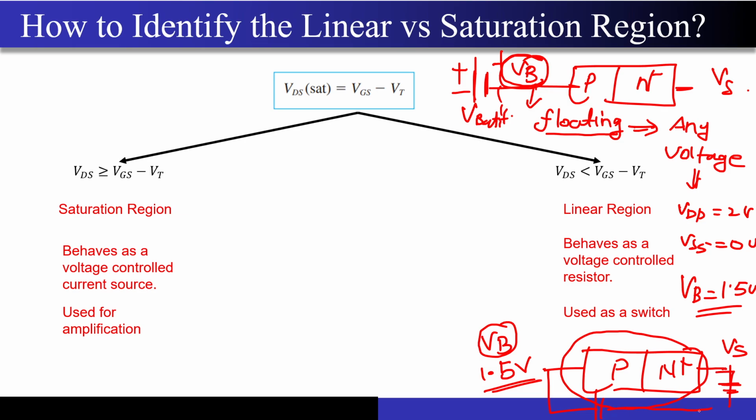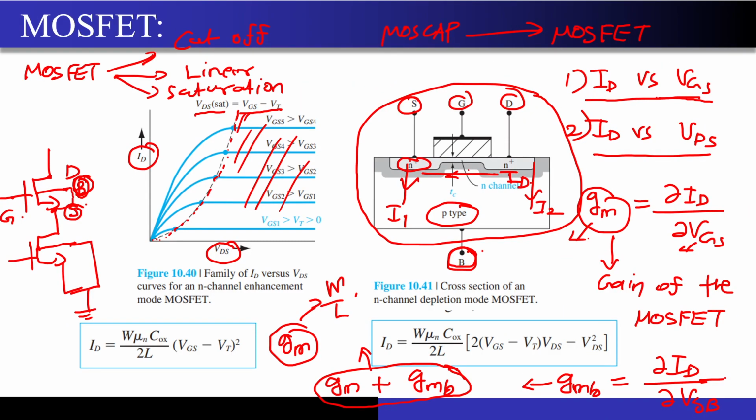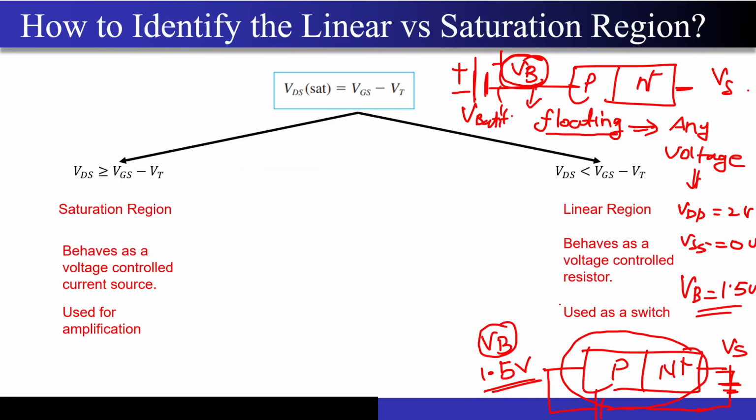And did you want to do that? Definitely not, because I already told you, I don't want any current to flow like I1 and I2. I only want a horizontal current, I don't want any vertical current in my device, right? So this is the answer that a semiconductor person will give you. This node will become floating, it can take any voltage. I don't want this node to have an arbitrary voltage, so that's why we generally take this body terminal and short it with respect to the source, right?